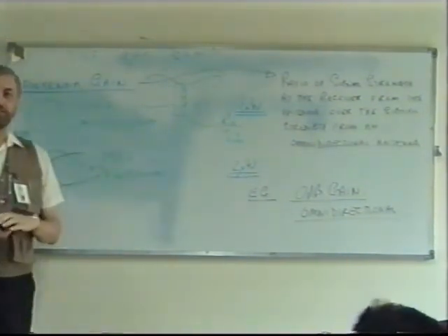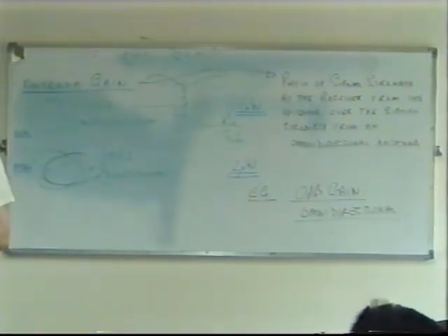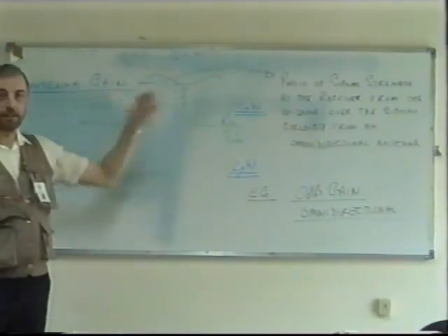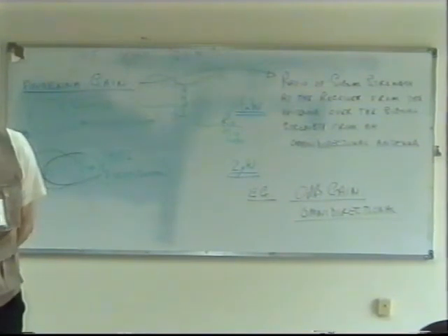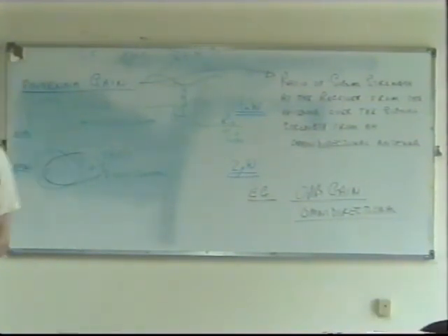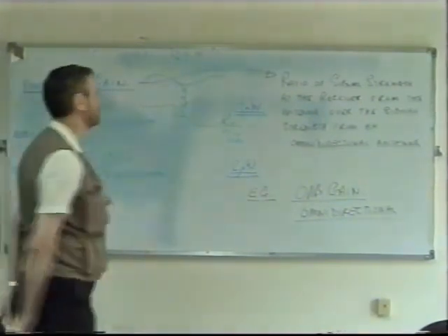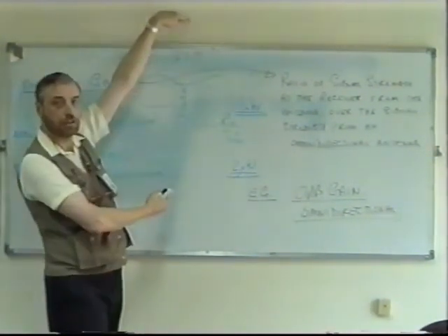If somebody talks about omnidirectional, it should be 0 dB. If it's a proper omnidirectional, it means literally in all directions. What about in the VHF, we have a stacked array like this, it is written plus 3 dB. Plus 6, looks like what we have in trunking. Now it is 6 dB. But they do that by cutting out the radiation above and below.